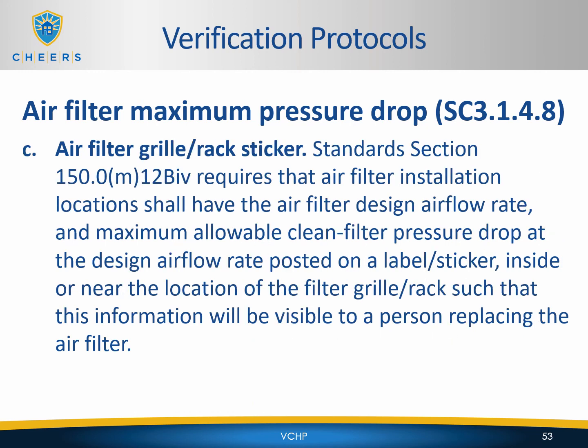Air filter grill or rack sticker. Standard Section 150.0(m)12B4 requires that air filter installation locations shall have the air filter design airflow rate and maximum allowable clean filter pressure drop at the design airflow rate posted on a label or sticker inside or near the location of the filter grill or rack, such that this information will be visible to a person replacing the air filter.